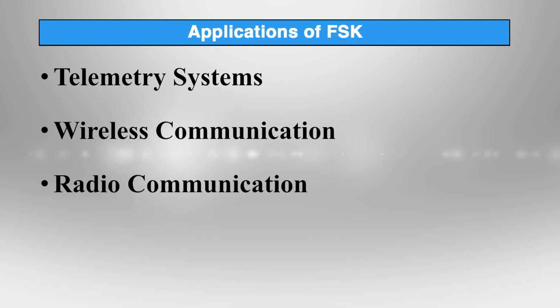Application of FSK: Telemetry systems. FSK is widely used in telemetry systems for transmitting data over long distances in noisy environments. Wireless communication: Older wireless communication systems, including some early cellular networks and wireless data modems, used FSK for reliable data transmission. Radio communication: FSK is employed in radio communication systems where amplitude distortion is prevalent.